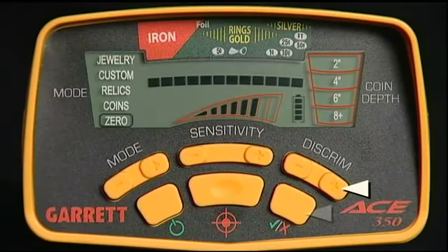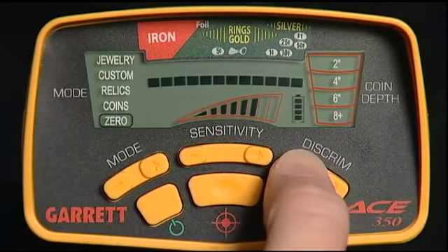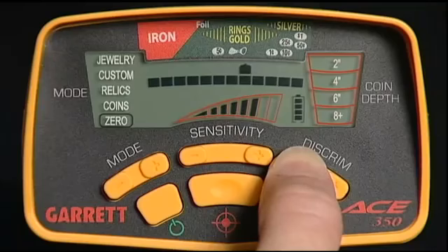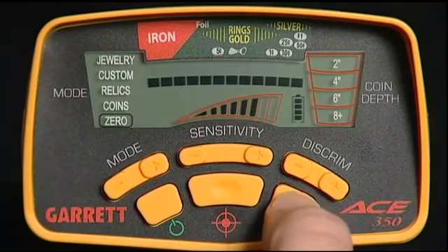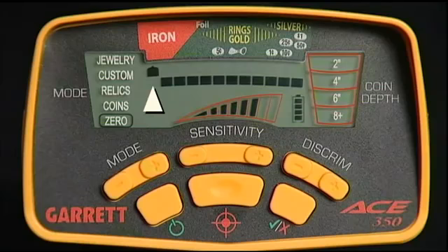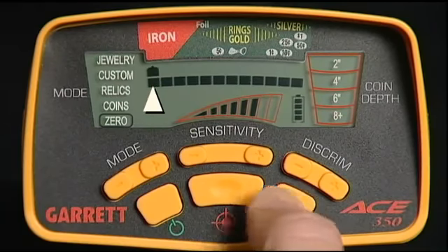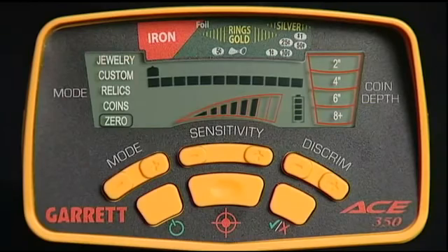Through use of the discrimination and elimination touchpads, specific notches can be created by adding or removing targets from acceptance in any operating mode. There are two methods of setting discrimination notches. You can use the discrimination touchpad to move the cursor and activate the specific segment of the upper scale corresponding to the particular target to be detected or ignored. Then press the elimination touchpad to turn the segment off, or use the same pad to turn the segment on, depending on your discrimination choice for this specific target.